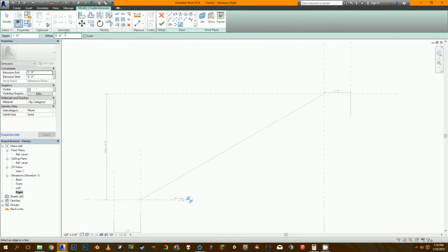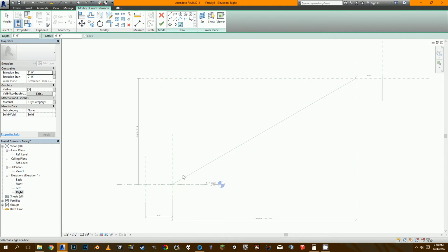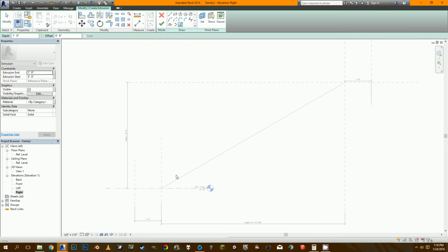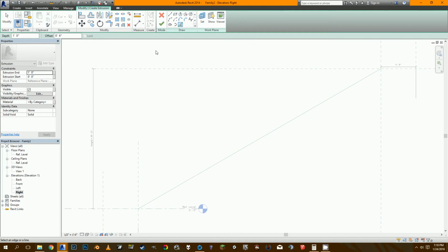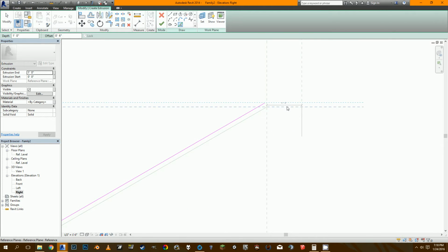do pick lines. So I'm assuming that little base piece is about 6 inches. And again, this isn't for construction drawings or anything. This is just for design drawings, or just to get your space requirements. So I'm not worried about how accurate this is relative to an actual escalator. I do know somewhat that the amount of space that it's taking up is the same, so I think that's good enough. So again, use pick lines and 6 inches, and just go here and here and there.